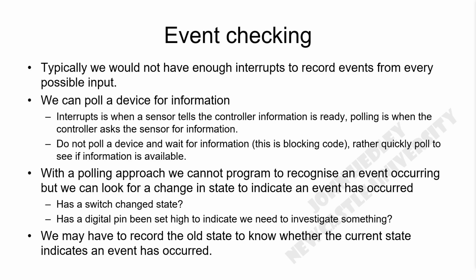As an example, consider we have an array of data which our sensor needs to send to the microcontroller, although we do not know when this data message will be ready. We could program the external hardware to set a digital pin on our Arduino to high if the message was ready to send. Our Arduino program could then check if this digital pin was high, and if so, our service routine would then read the message. Thus, we have not wasted any time waiting for the hardware to collect the data.